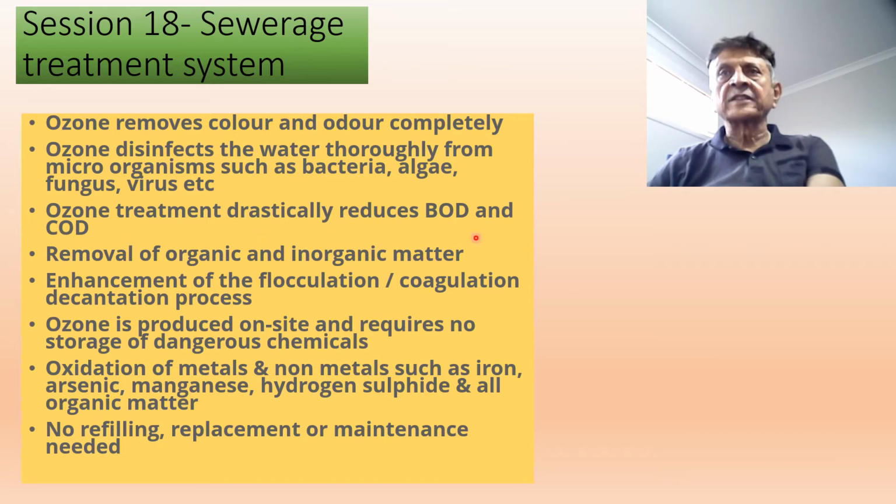Removal of organic and inorganic matter. This is of course related to both the BOD and the COD. The organic material causes the increase in BOD. The inorganic matter causes the increase of the COD. Enhancement of the flocculation and coagulation process: because the ozone denatures soluble protein, the denaturation process will result in either flocculation or coagulation, so that the precipitate will settle. You can just decant the water, leaving the precipitate as a sludge.